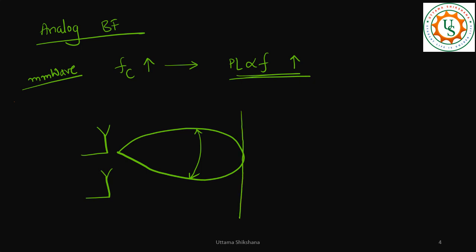Okay, let's say now I have got two UEs. Let's say this is UE number one, and this is another, UE number two. So in that case, what is happening? Both the UEs are addressed with a single beam. But when we are addressing both the UEs with a single beam, we need to have orthogonality, right? Because both the UEs are getting the similar signal. Somewhere we should have the orthogonality. So how can we achieve orthogonality? It could be time division multiplexing. So maybe at different times we can address these two UEs.